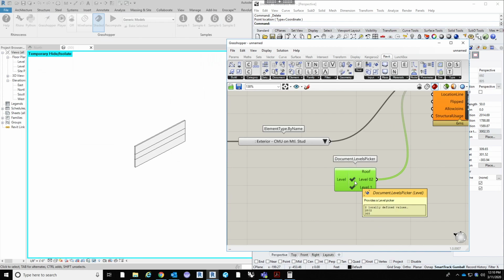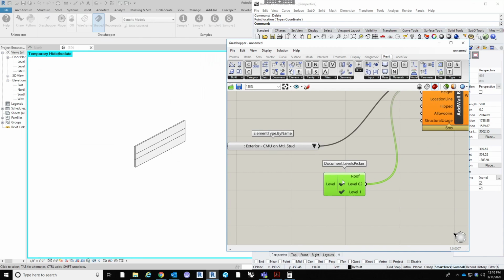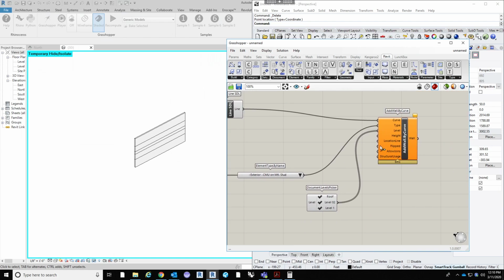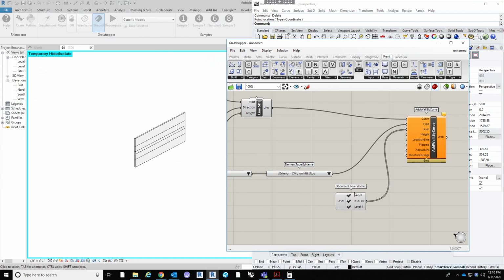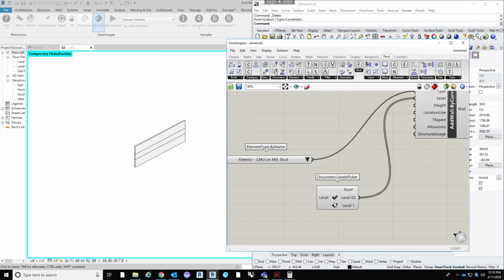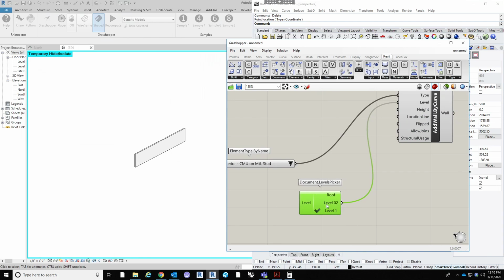So if we do both, yes. If you right click, do the checklist, you can check more than one, and that actually starts to create 3 different types of walls. Yeah, and this preview is just saying that highlighted walls overlap. So that means that our heights are larger than the level heights. But let's just keep it to level 1 for right now.